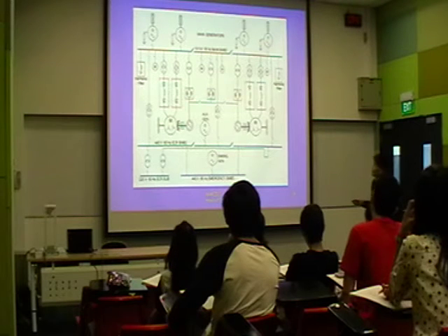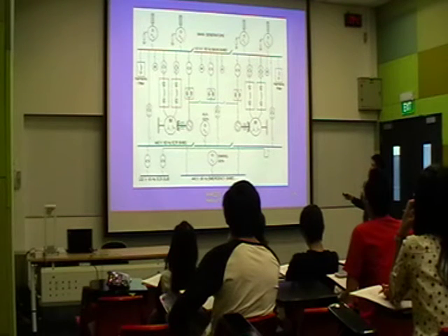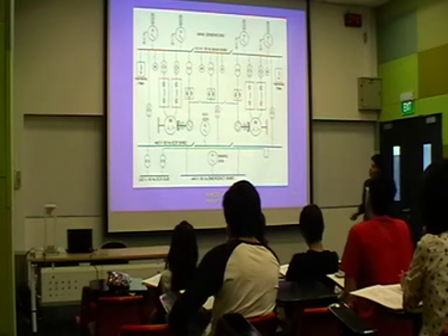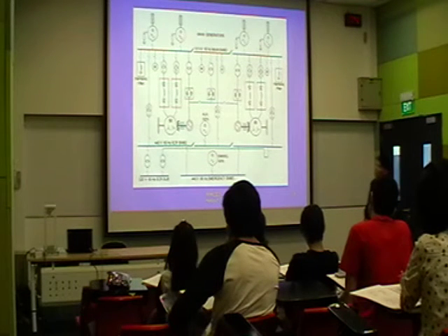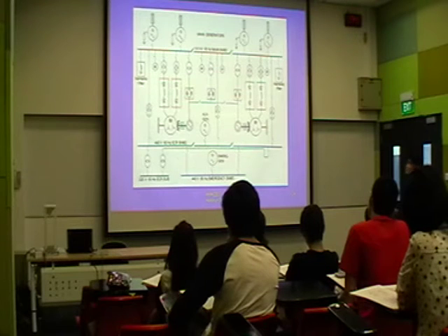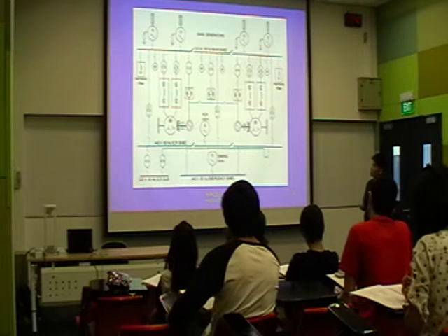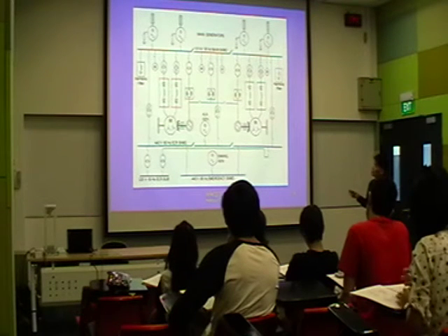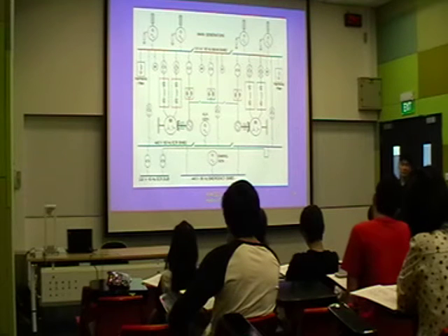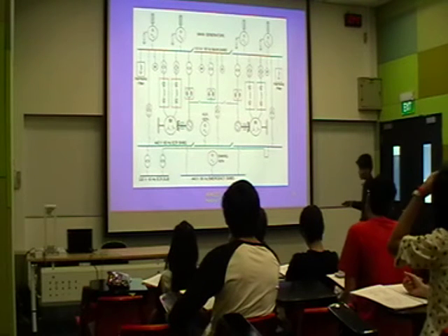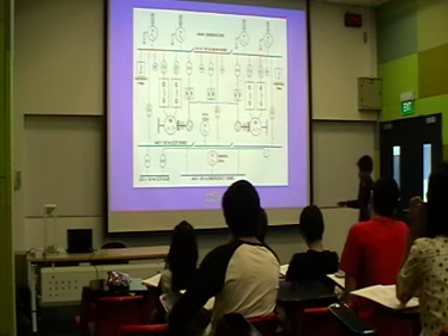Below that, there's always a further step down. You can see it's 6.6 kilovolts stepped down to 440 volts. There are a few generators for redundancy, for the fault tolerance aspect, just in case one generator fails. If I'm not wrong, the classification rule says you must have at least two or more. And there are always emergency generators.